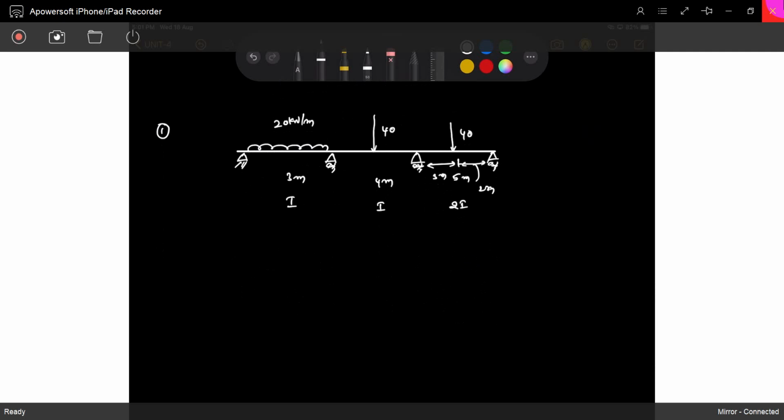First we have to assign A, B, C, D. So first find the fixed end moments. If the supports are fixed, everything is fixed, and no rotation is allowed. Those are the fixed end moments. In reality, rotations are allowed at B, C, D and A also. So if rotation is allowed, how much moment is altered? There is a distribution factor.